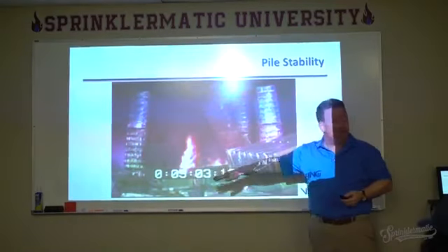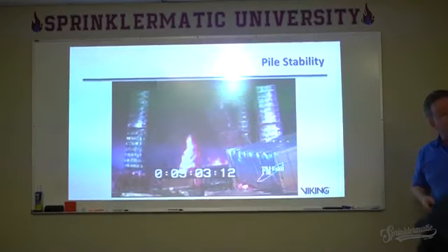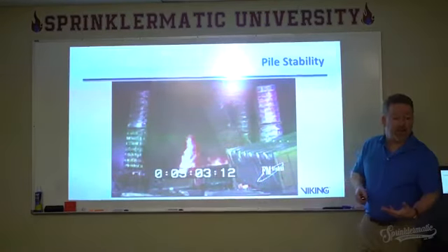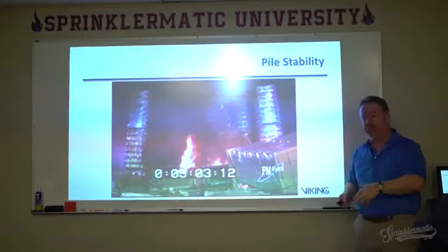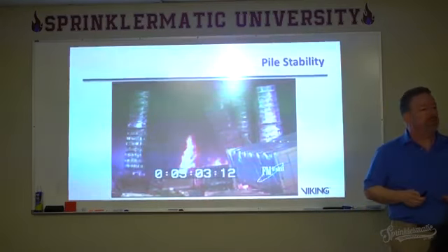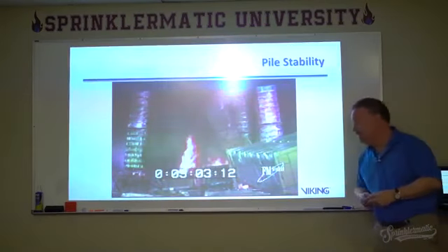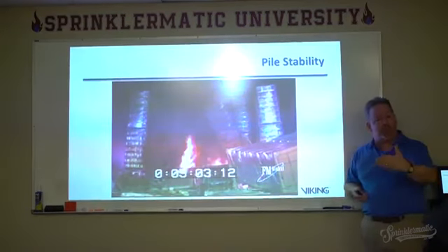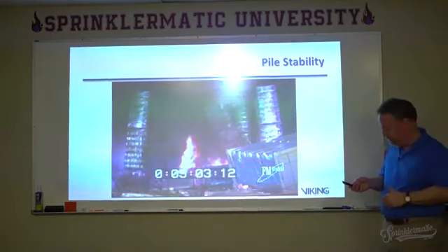If the piles are not stable and have a tendency to fall in on themselves, you have a smothering effect on the fire. It actually helps in fire control if you have an unstable pile, because everything will eventually fall in on itself and smother things. It's still a challenge to get to the base of the fire, but for the most part, it's not as big a challenge as if you have a stable pile. So the designer is going to need to take a look at that as well, and that's where the wood pallets and the reinforced plastic pallets need to be considered.